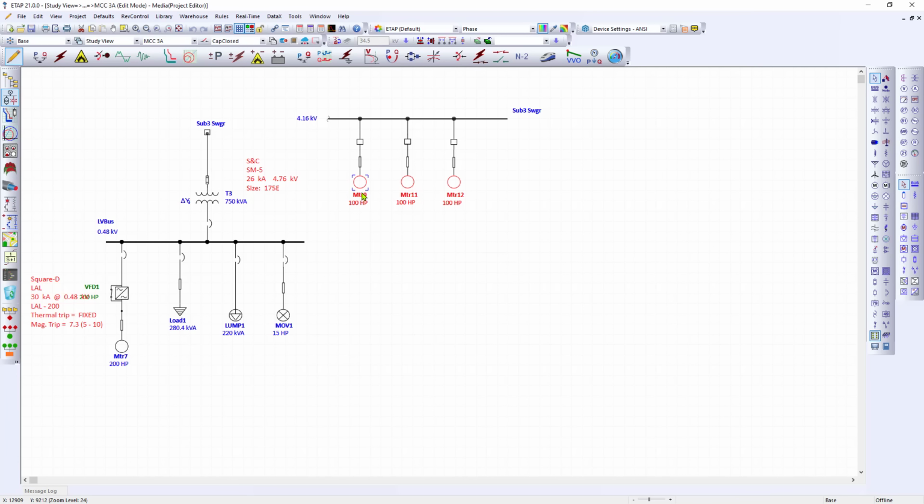So this is our copy data and paste to many devices. So you just have to highlight the ones and select the bracket, and it's easy to copy and paste the data over to different elements. And if I want to add one more, I can highlight this branch, Control-Shift-Drag. Control-Shift-Drag duplicates that motor, that whole branch, and I've created a copy from one of my existing ones. Again, that's just done by highlighting and clicking Control-Shift, and then I can drag it over and duplicate that equipment along the bus.